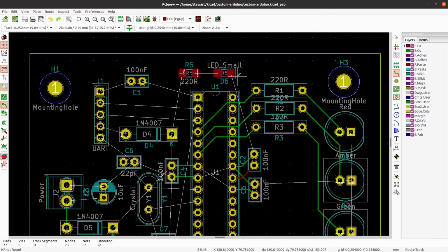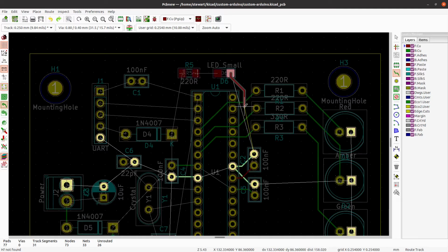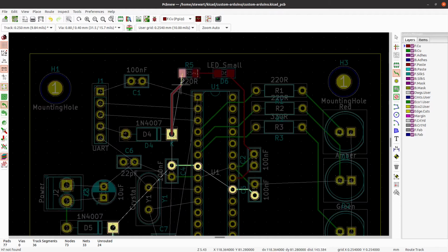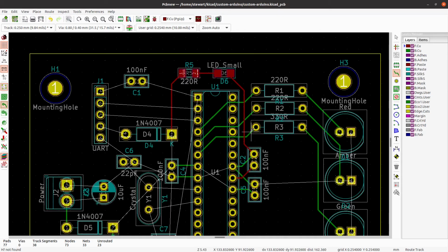This is a surface mount device, so it doesn't have a via, doesn't have a hole going through to the bottom layer, so it has to be on the top layer. So in that case, it doesn't need to go through there at all. So let's do all these actually, because it's going to dictate somewhat what to do with the rest.